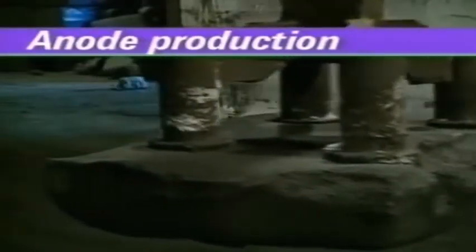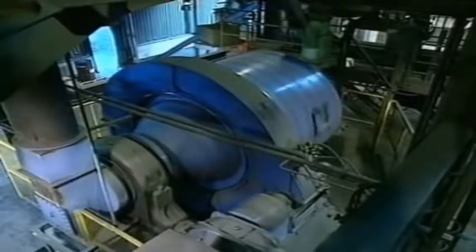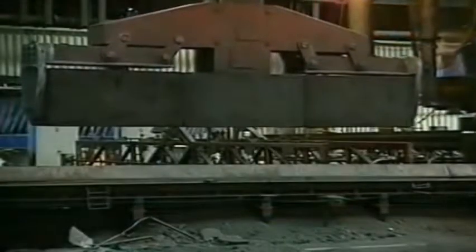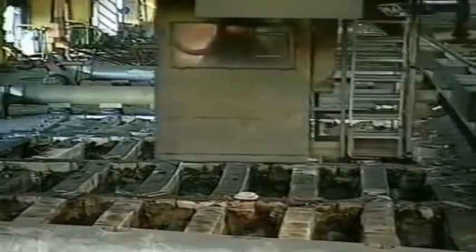The remaining carbon is broken off the old anodes, crushed, mixed with new coke and pitch, and pressed into shape. The newly pressed anodes are baked for about 24 hours in gas-heated pits. This produces electrodes which will conduct electricity and not crumble away in the cells.